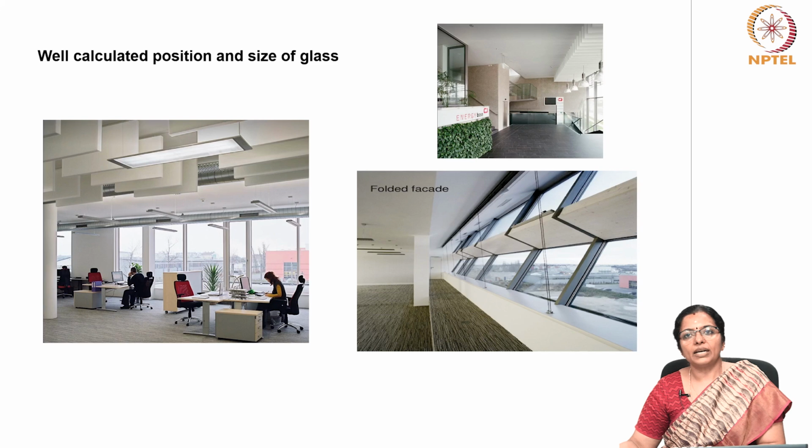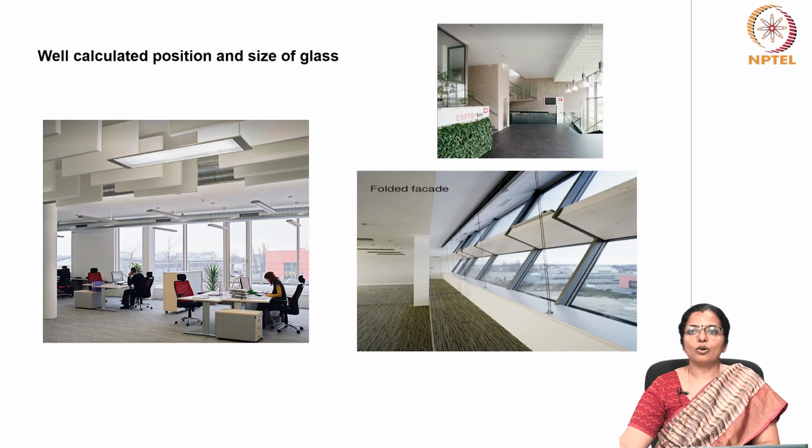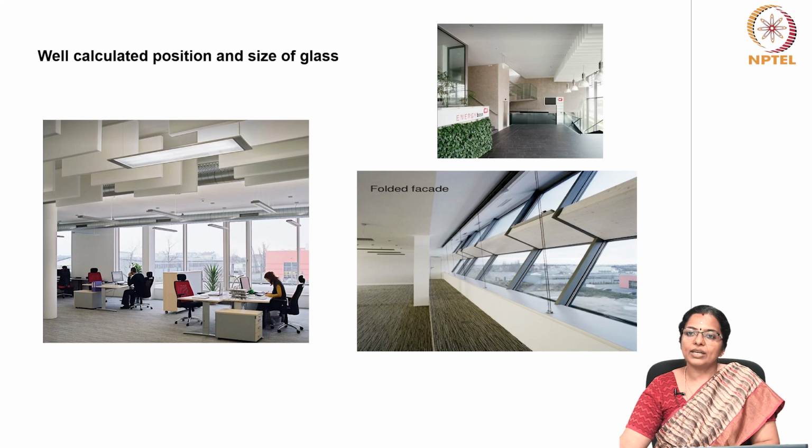In winter, the building combines solar preheating of ventilation air with heat recovery in a very different way. Ventilation air flows laterally from the north side to the south side of the building, then is overheated to the desired indoor temperature by the space next to the glazing, which functions as a solarium. This overheated air passes through the heat exchanger where it is particularly effective in warming the incoming fresh air.